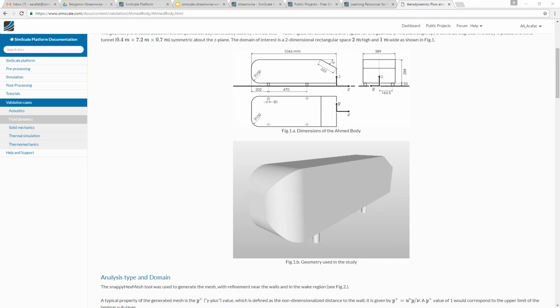The question is: in calculating local flow velocity, I assume the probe alignment is detected and the tunnel flow is perfectly lined up with the tunnel axis, right? Well, the probe alignment is of course detected, so the position and direction of the probe are determined at any instant in time, and the movement of the probe itself is also taken out of the measurements, because the velocity of the probe can change the velocity data, so this is calibrated out of the data at the end.